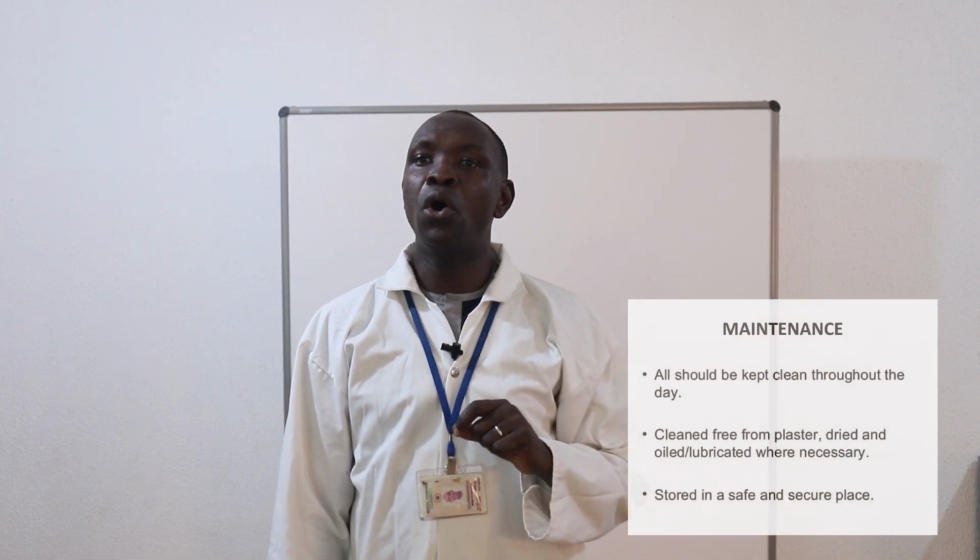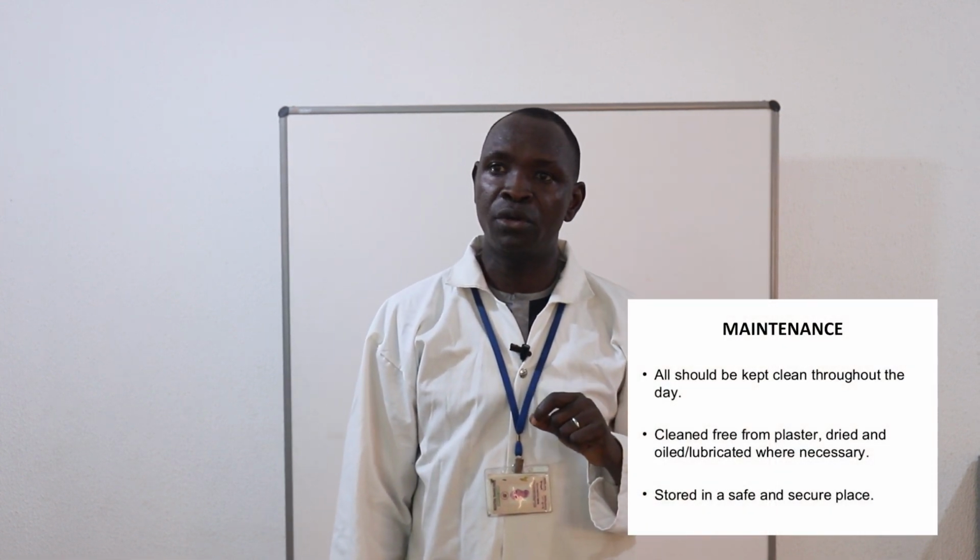You need to use a hammer. On this note, I want to talk more on the maintenance of these tools. All tools after work should be kept clean throughout the day. Clean from plaster, dried, and oiled and lubricated where necessary, especially the stainless float which I earlier mentioned. And they should be stored in a safe and secure place.